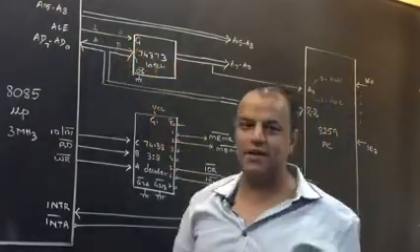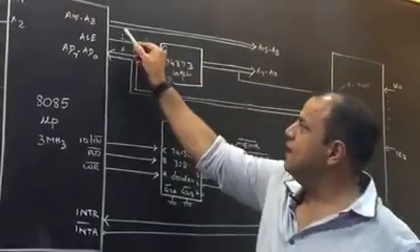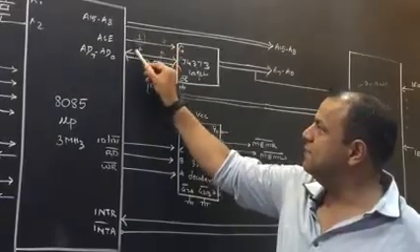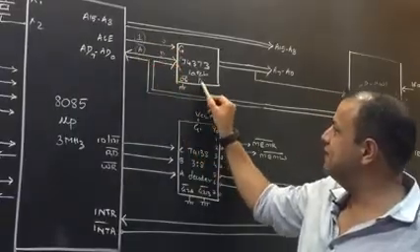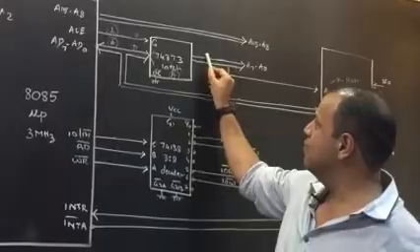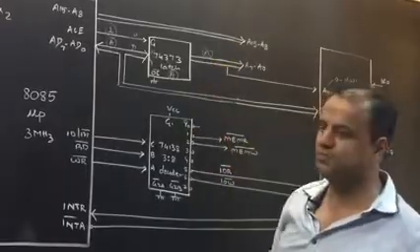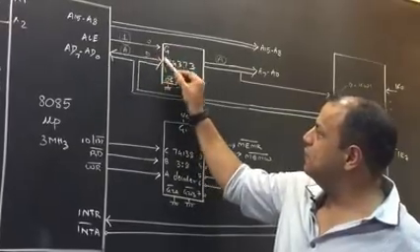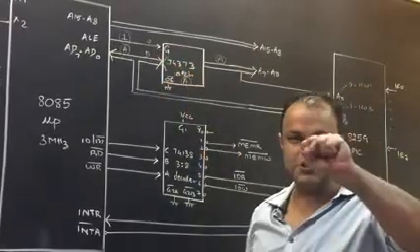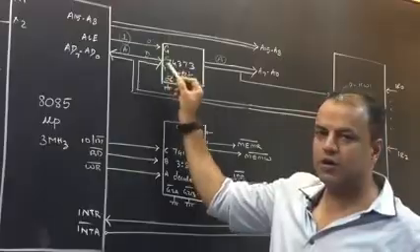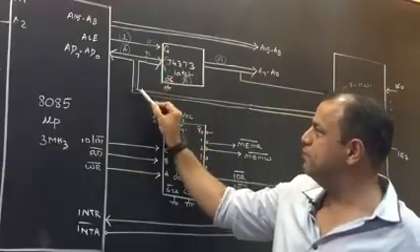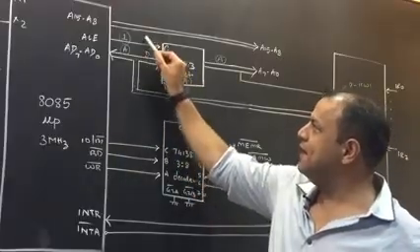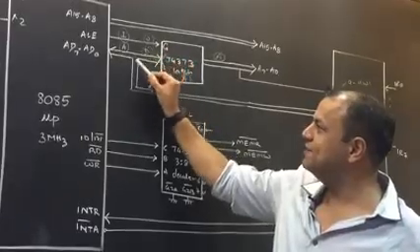Since I have connected gate with ALE, when ALE is 1, the bus carries address. Address will be captured by the latch. What will come out is also address. Please tell me, did you understand this? Now, when gate becomes 0, the gate of the latch is shut. Input is not allowed to enter inside. Input will come out from here. When ALE is 0, the bus carries data.